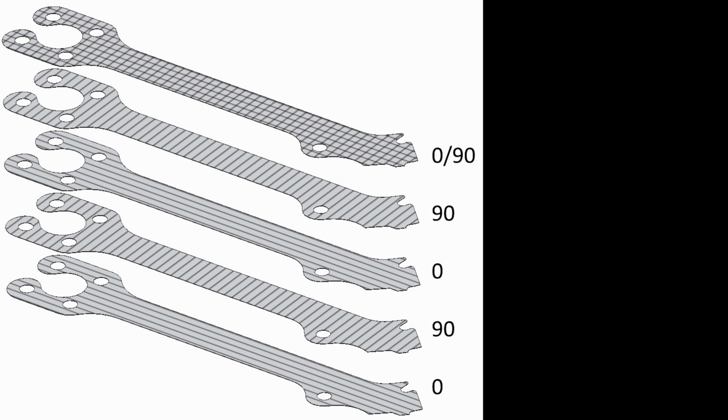Carbon sheets are typically made of layers of actual fibers, and these fibers can be oriented and designed however the manufacturer wants them to go. Typically, only the top and bottom layers are woven, just for cosmetic purposes. They also have strength qualities, but they're mainly cosmetic and don't contribute quite as much to the final carbon product and its properties as all the other layers inside.